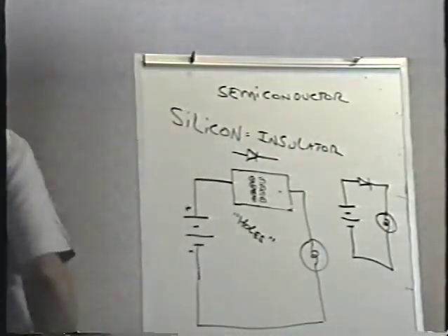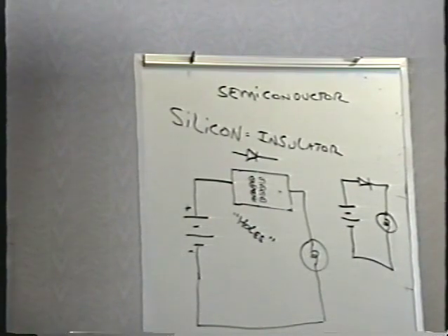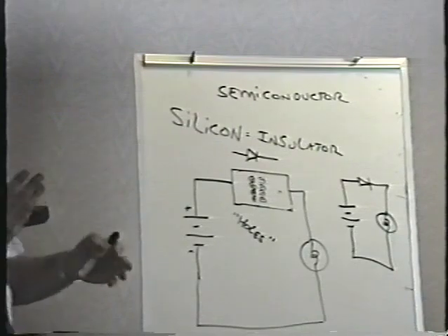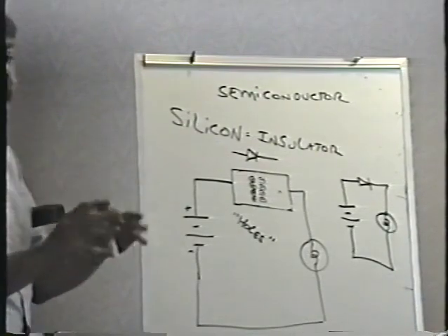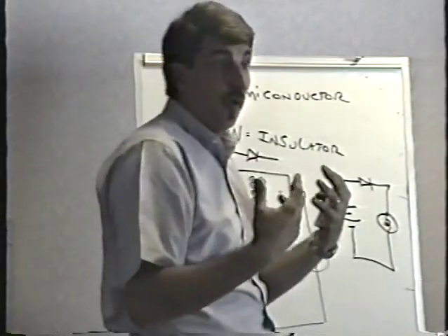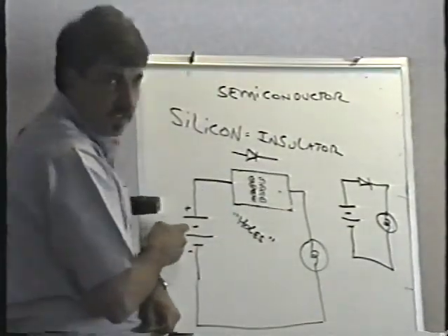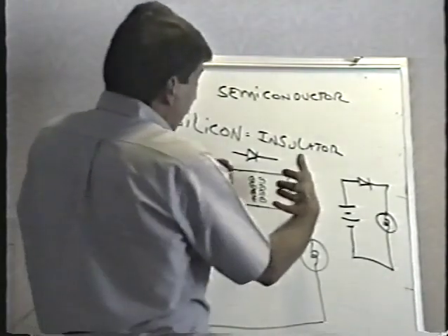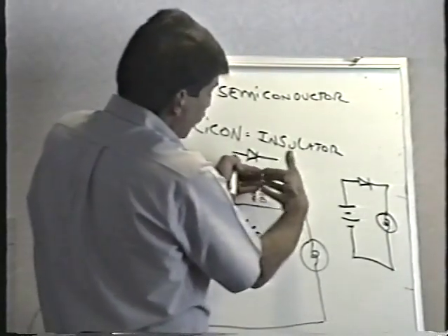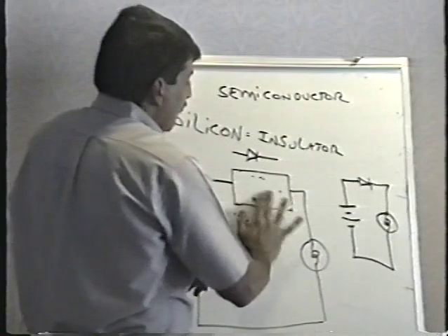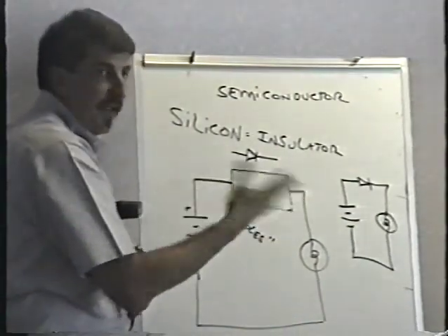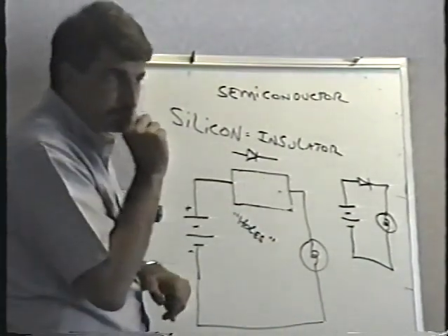It's like, if I close this door here and I try to hold it, if one person is pushing on the door, I can probably hold it. But if I've got enough people pushing on the door, you're going to push through. Same thing here. If there's enough pressure, enough voltage, and it doesn't take very much, the electrons and the holes pushing on that door, on that PN junction, literally knock it aside, and the diode starts to conduct.